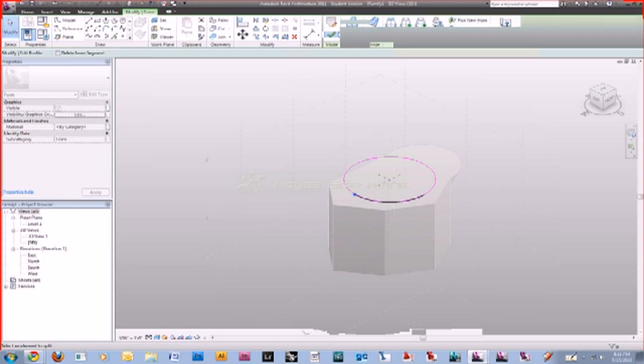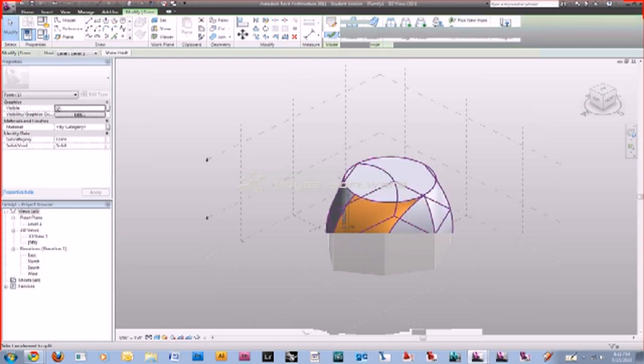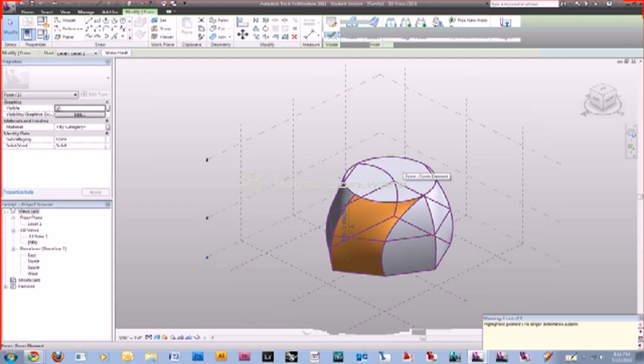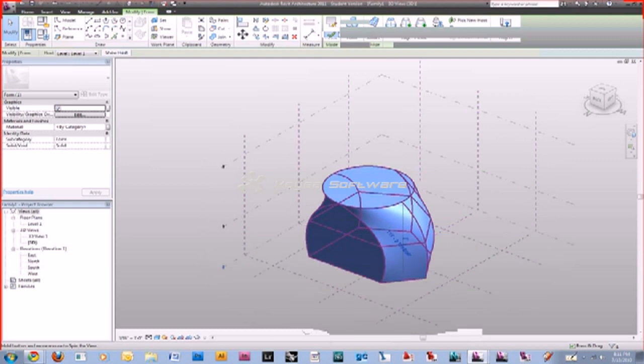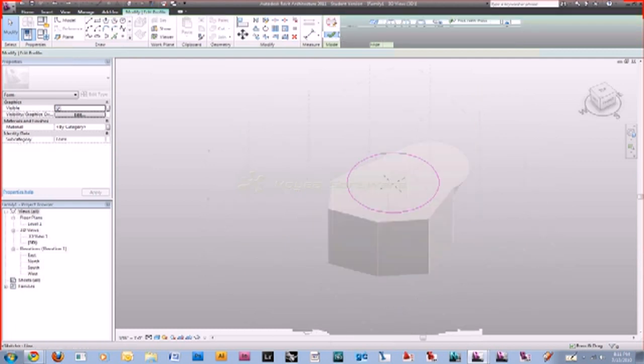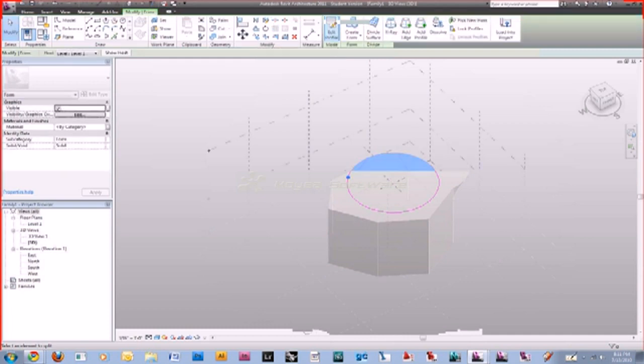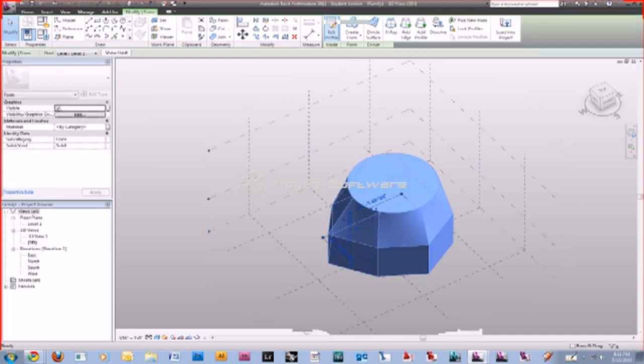So if you had a polygon with 10 sides and you wanted it to extrude up to a circle, if you put 10 points on the circle, then theoretically the shape becomes more smooth as it goes up. Yeah, so I can split this a few more times, even more than I need to, just to make sure. Yeah, and it's just going to find the best solution. You're giving it options, and it's going to find the solution. Then I hit finish. It looks so now it's starting to look a little bit better and not as wonky.